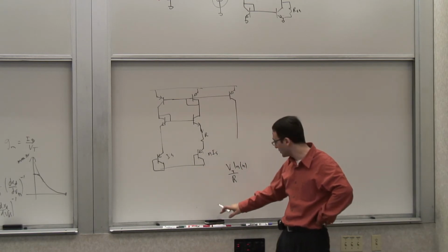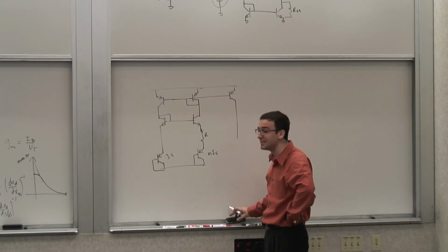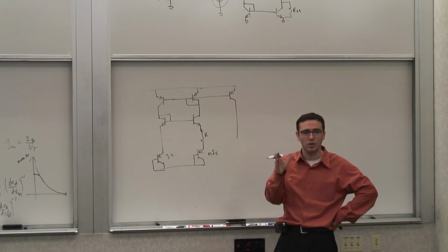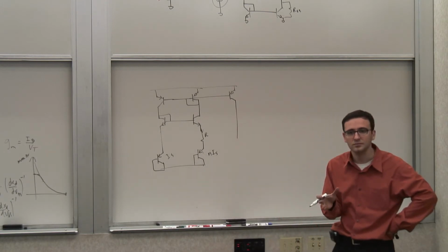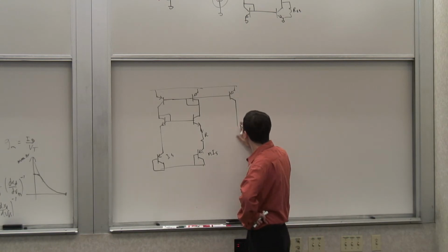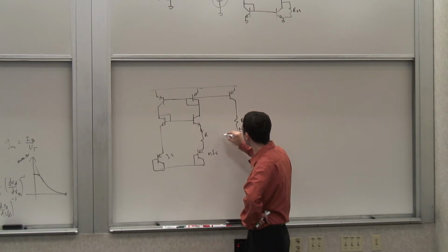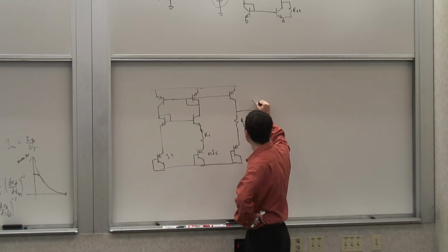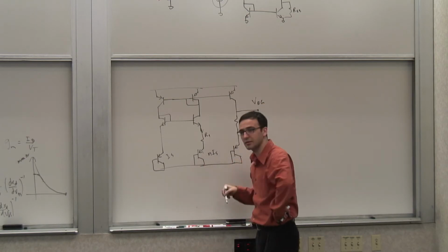Now the last thing we did was that we saw that the VBE itself had a component proportional to VT. And on the opposite side, we said, well, if we add this VT, let's say this is R1 and R2, to the VBE, we could actually extract a voltage that was proportional to the band gap, if you make this the right ratio.